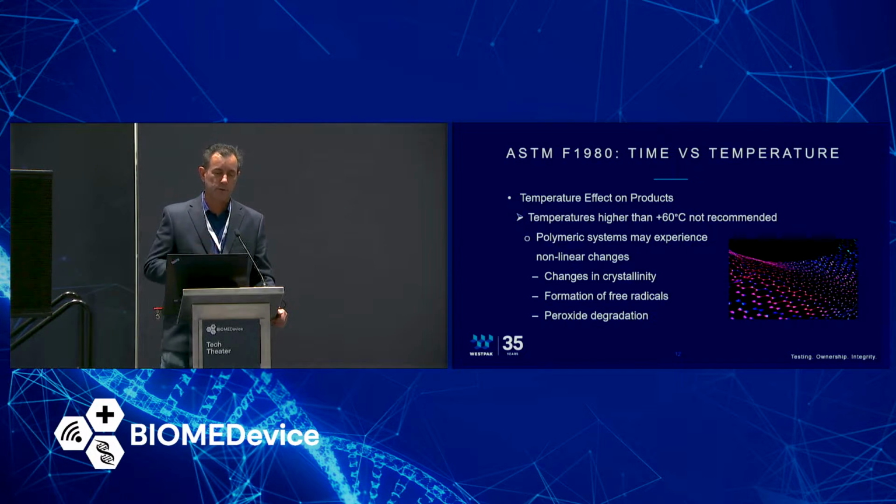So we want to stay out of that. We want to stay within a range. So what would that range be? Well, typically the glass transition temperature. You can think about that. Glass transition temperature, the temperature that you age at, you should be below that so that you don't have any defects or false positives.